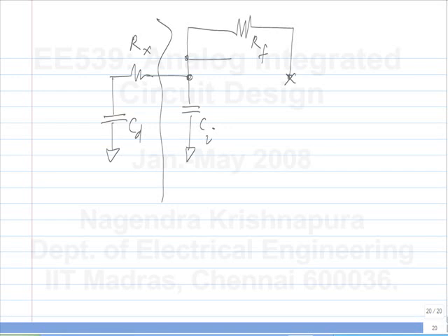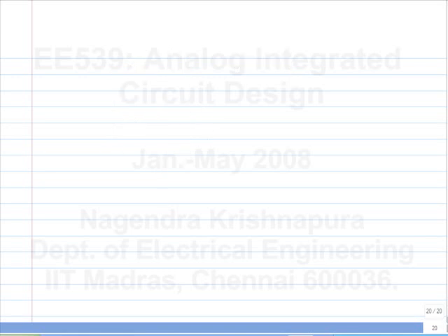But if you do have this, you will have a capacitive path, capacitive divider. So this will have very little phase shift at high frequencies. You can go and work it out and see, but because you have a capacitor here, you will get additional phase shift. So it's not as effective a way of stabilizing the circuit as the others. So we saw several ways of stabilizing this.